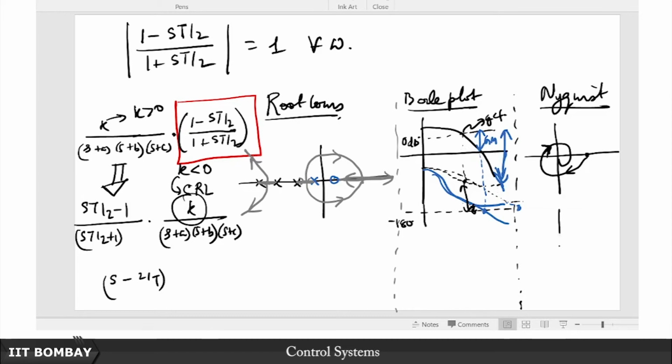Remember, maybe the original Nyquist diagram probably looked something like this, but now if you rotate this, whatever was 180 degrees away somewhere here has now come here. So you have twisted this and gotten this point to come here. That is the net effect of this pure rotation.